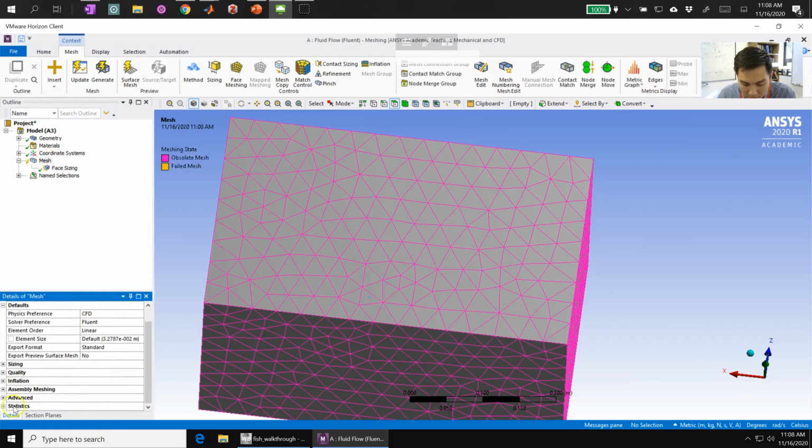The statistics of our base mesh were that we had about 8,700 elements. This is the number you need to keep an eye on. This is the number of faces, number of volumes, number of nodes. You want to keep this number low, but you need to have a sufficient amount of resolution. This is the balance you have to find as you're developing your mesh. Our target for this simulation is going to be about 180,000 elements. I think the code will allow you to get up to about 350,000 for the student version. Obviously, the more elements you have, the longer your run is going to take.